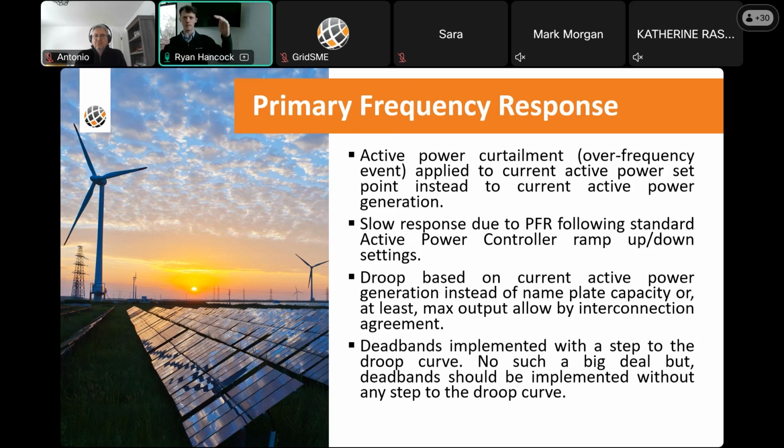So going back to the scenario where instead we're producing 45 megawatts, so we're once again operating at about half, what may happen is, if you're not using the nameplate, you'd actually reduce less than you should in order to accommodate that response based on the frequency event that's occurring. So what should happen is, even though you're producing 45 megawatts, you're actually looking at that 90 megawatt nameplate. So you calculate out the 30. From 45, we need to scale it back down to 30 to provide the proper response for that frequency event.